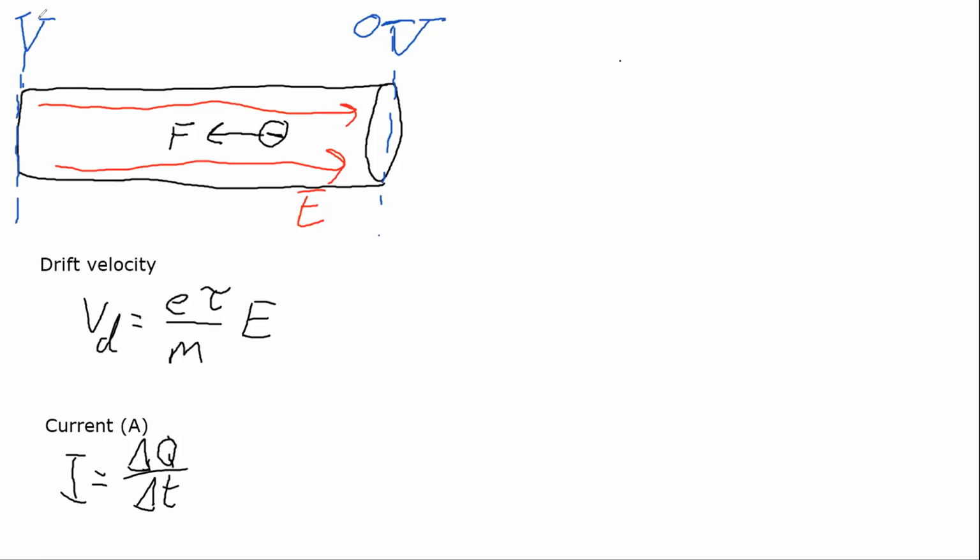And we got a little bit specific here. In this equation we have e, again the charge of the electron, 1.60 times 10 to the negative 19, my fundamental unit of charge. So that's e times n. n is the electron number density. How many electrons do you have per unit volume? Times your drift velocity, times the cross-sectional area of the wire.